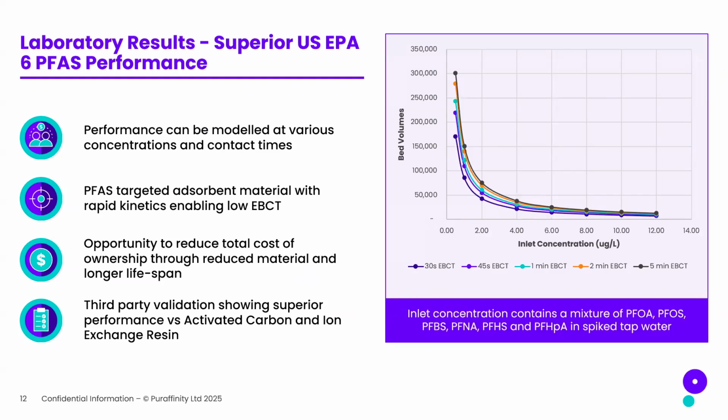There's significant data that has been developed. If you notice some of the concentrations here, up to as high as 12 part per billion, and the lifespan of the material is certainly dictated, similar to other products, by the concentration. So we have various contact times and concentrations depending on the compounds and the water quality. But again, low empty bed contact times, measured in seconds rather than in minutes, which again will reduce the system size.